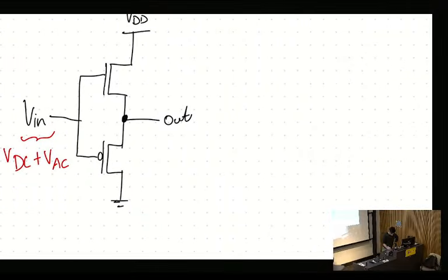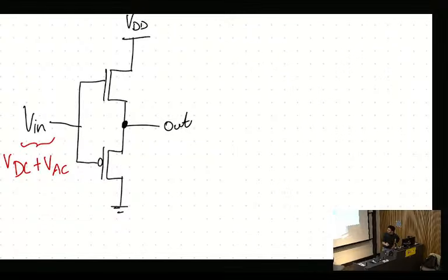So now let's analyze what happens in this case. If the signal is positive, what happens? If the signal is positive, the NMOS turns on, and I pull signal from VDD to the output, right? So if this is, say, a high signal, I'll just draw what class B looks like. So the gate signal, we bias it with just a bit of gate signal.